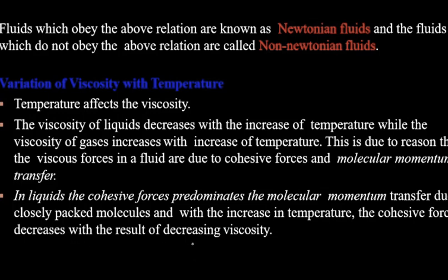Just remember three points. The temperature surely affects the viscosity, the viscosity of a liquid decreases with increase of temperature, while in gases it increases with increase of temperature. Why?